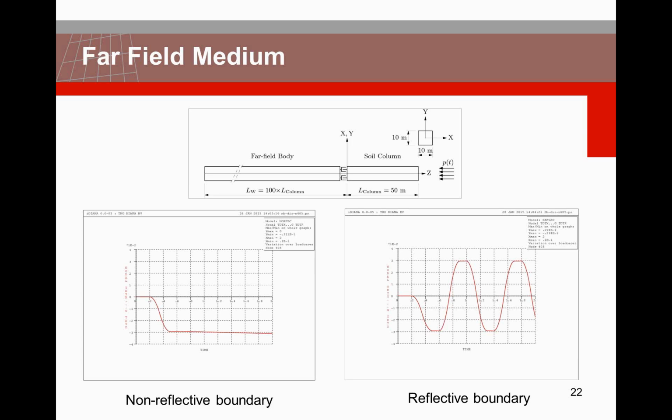But in case you have not so much damping, you have high wave speeds, and you want, for instance, to do a full seismic analysis of 20 or 30 seconds, you're going to need to do something at these boundaries to avoid that the energy stays in the system and keeps reflecting and giving you inappropriate dynamic behavior, because you see a lot of things which are physically not there, but due to your modeling. Without non-reflective boundary conditions, you will end up with maybe way too high stresses and cracks in your construction, which may not occur in real life.